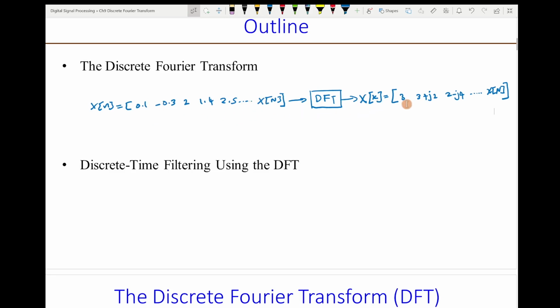You can find the frequency content, which is maybe 100,000 data points again. But maybe the first 100 data points are important, very strong. All the other frequency components are very weak. So you can eliminate them, filter them out, and then reconstruct the signal back again, and it will come out almost the same as the original.